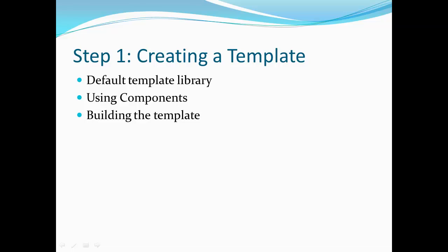Once the data has been imported into Corridor Modeler, it is then possible to create the existing template needed for the project. There are a number of bundled components that are available for use in creating your existing pavement and cross-sections that can be used when doing earthwork calculations. The existing data we imported is also available down the line when modeling the proposed condition in the cases of widening, for instance.